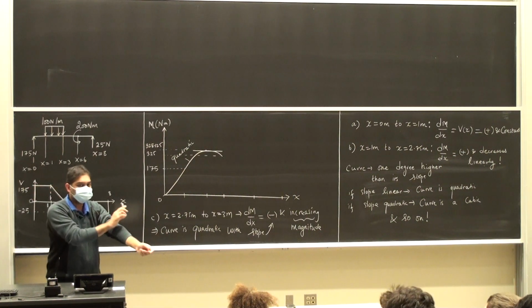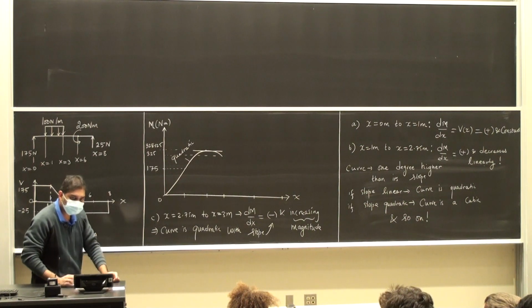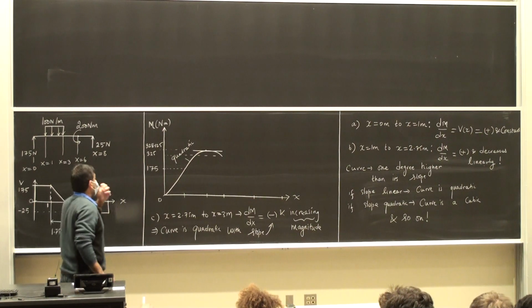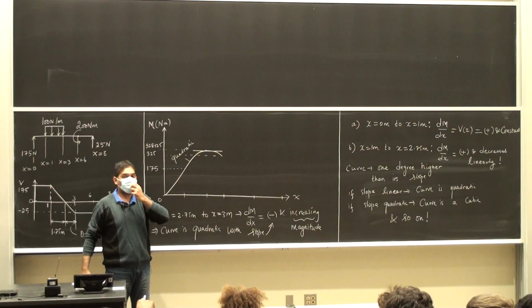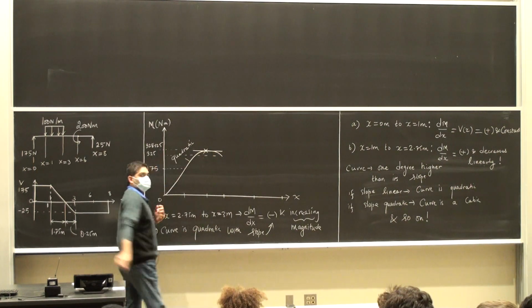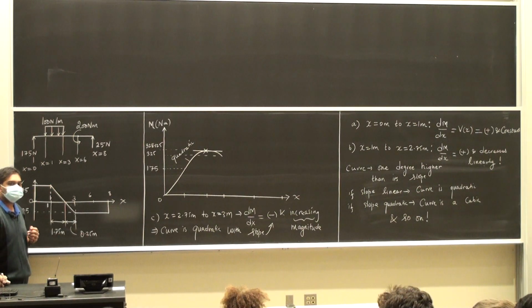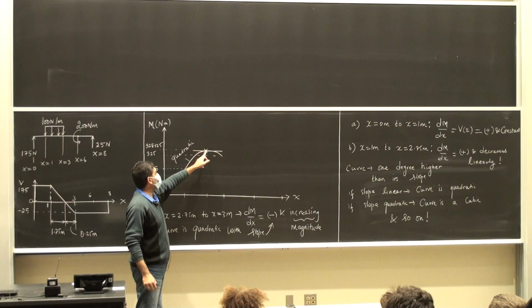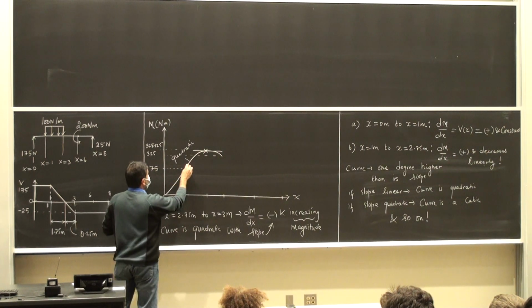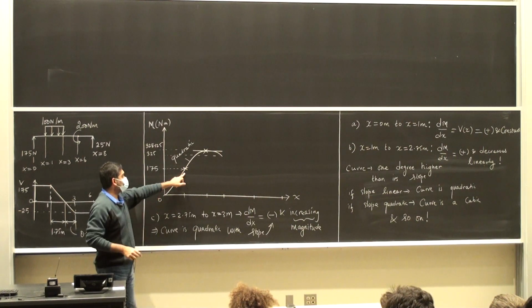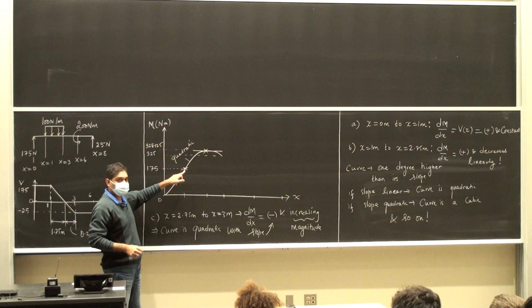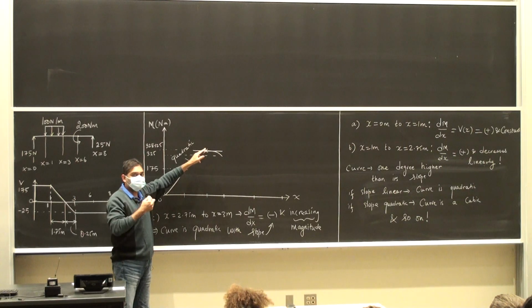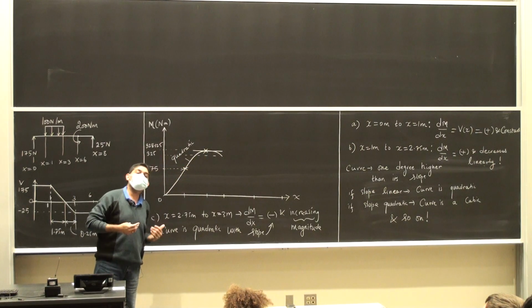Yes, sir. I have a slight confusion. Before we drew the quadratic curve, we went ahead and drew the straight line. No, the straight line says that the slope is 0 at this point. Do we pick up from that straight line or from the previous quadratic curve? So this curve ends here. This piece starts here. You see, the slope here is the same as the previous, so there is no discontinuity in the slope. This piece, starting from here all the way to there, is a quadratic. That tells you the evolution of the bending moment from x equal to 1 meter to 2.75.